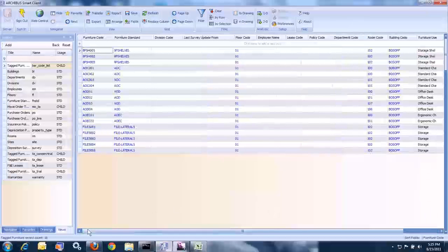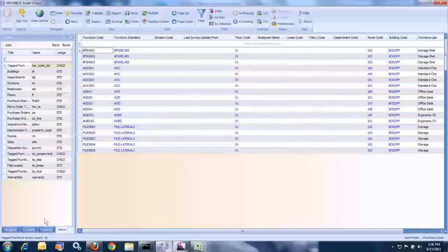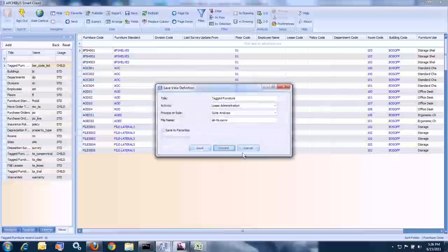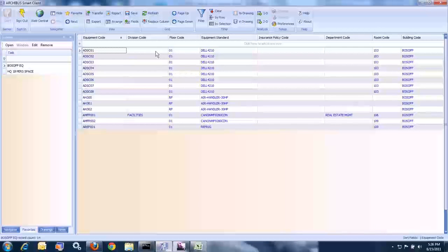So we've been able to also set up a tool that allows us to, whether that information is in the Revit model and we export it out to a spreadsheet or a COBie file or an IFC file, or if we have this information submitted to us in a proper format, which is to populate a spreadsheet that we've stood up for our contractors, we're able to identify any field in the database, be able to have them populate that data for us as they're building this building, input this data into ARCHIBUS, and be able to go ahead, create our SLAs, go ahead and stand up our on-demand work, go ahead and start to schedule preventive maintenance, assign these pieces of equipment to people, things like that.